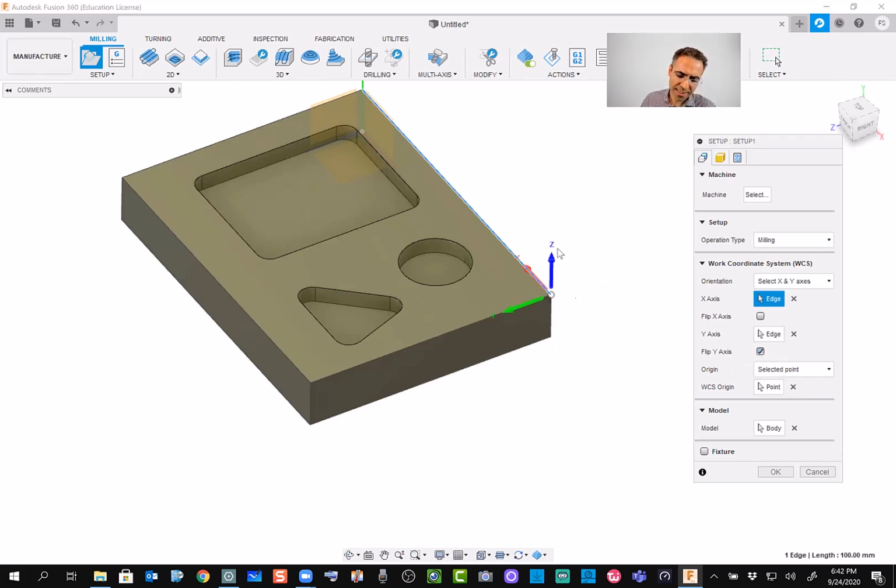Now my Z axis is in the vertical direction, up. This is more like a standard way of milling. However, it's okay if you select a different X, Y, Z, but later you are in trouble when you set up your machine. Are there any questions so far, guys? So all we did so far is just setting up X, Y, and Z at one corner of the box.